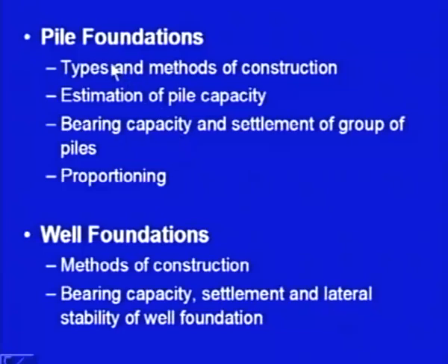After shallow foundations, we will move on to pile foundations. Pile foundations are the foundations which are given when the load carrying capacity of the subsoil strata is not that good, and we have to transfer the load deeper into the ground. So, shallow foundations are not sufficient, we have to give piles. They are a little bit costly, but the loads can be transferred deeper where the strong, competent stratum is available.